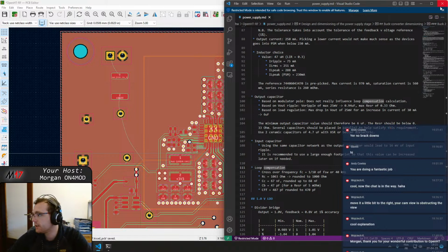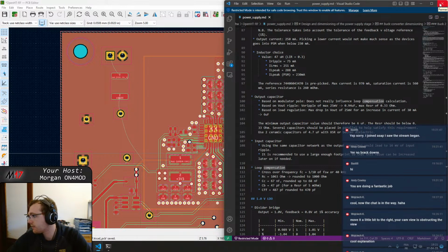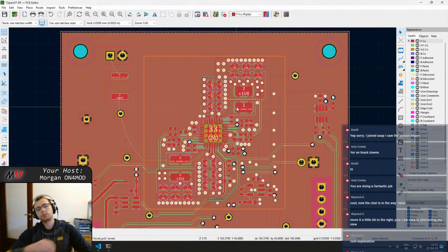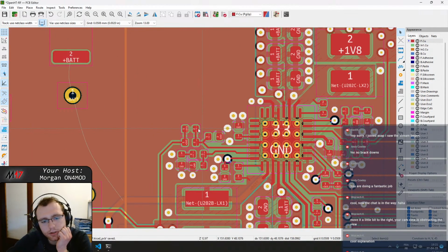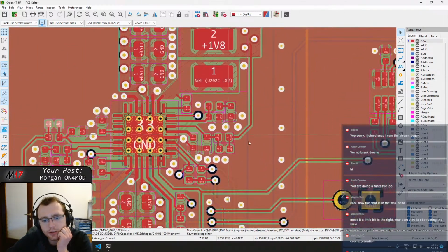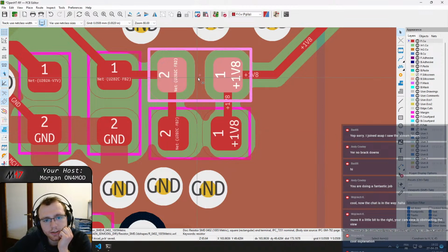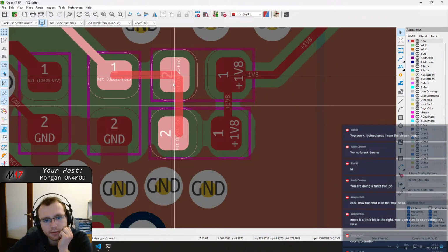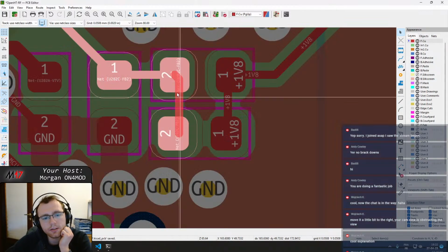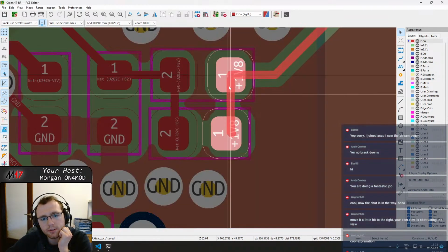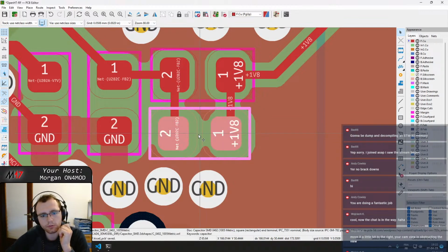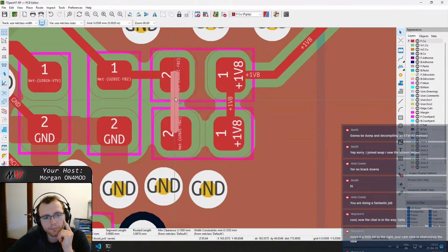I can't guarantee that before having it in my hands and testing it. So the most important thing is that we have all the footprints at the correct location. So this one here and this one here, that's the one that we were lacking, and that I had to add today. We still can update the value of the components later on if we want. That's not a big deal, it's easy to do. But we can't add footprints later on.